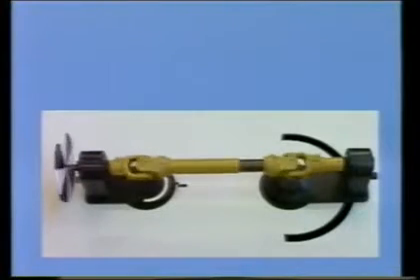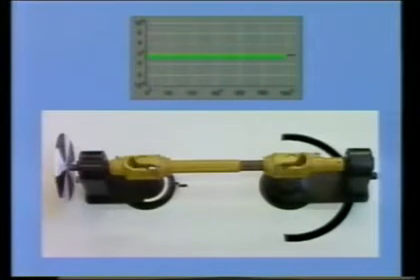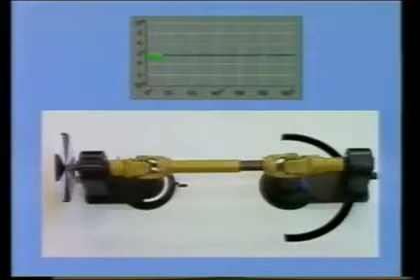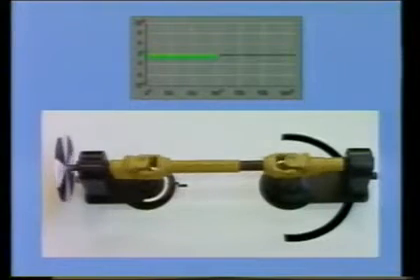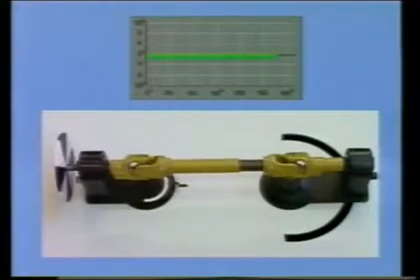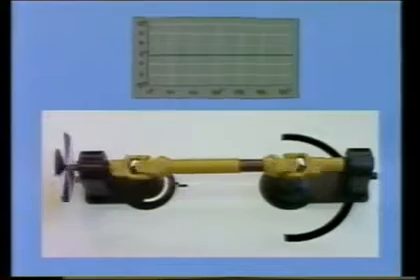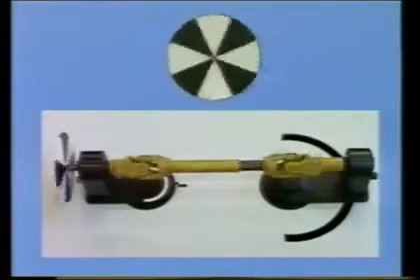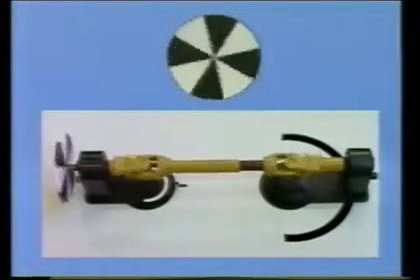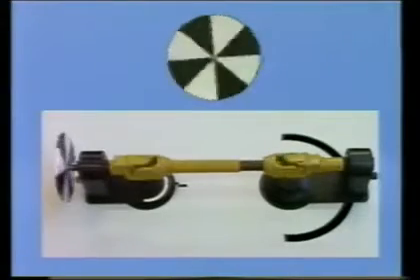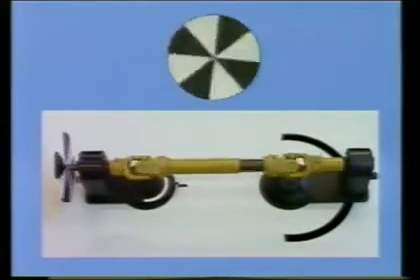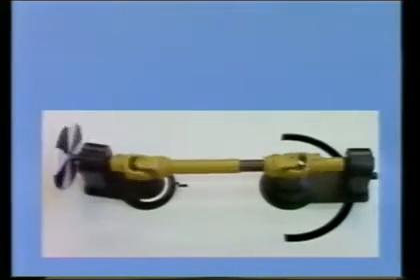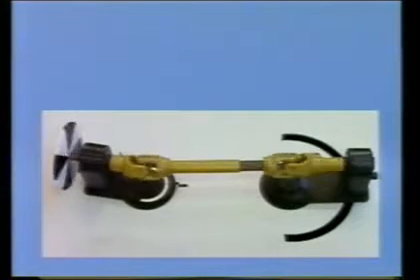When angled, the shaft transmits the rotary motion unevenly as the working angle increases. A lead or lag angle occurs in the driven joint. Here, the working angle is 15 degrees. The velocity variation is 7%. The velocity variation is virtually undetectable on the black and white disc and only has a negligible influence on the driveline components of the tractor and the implement.